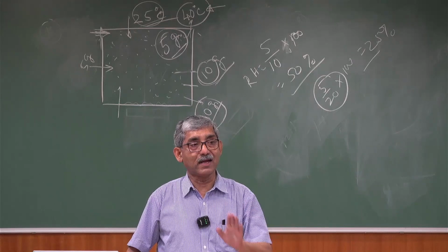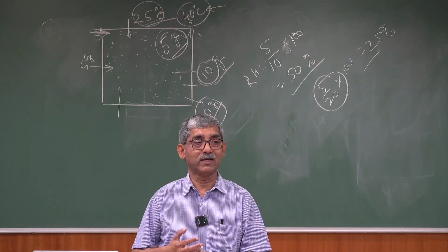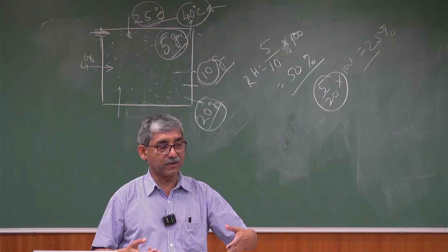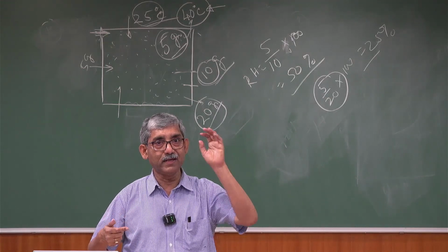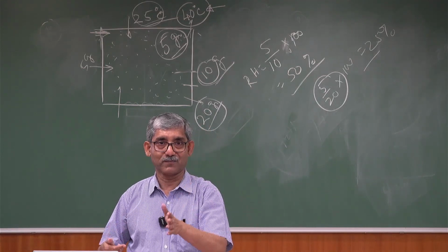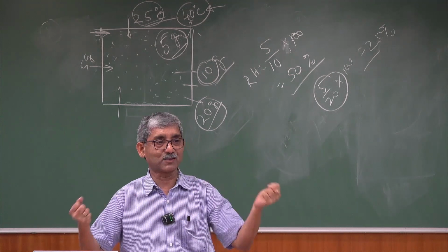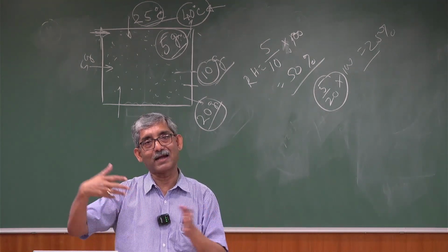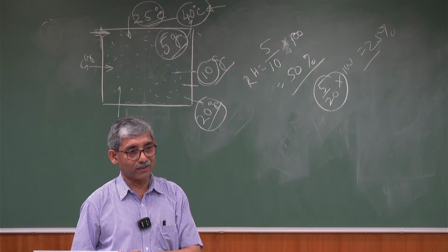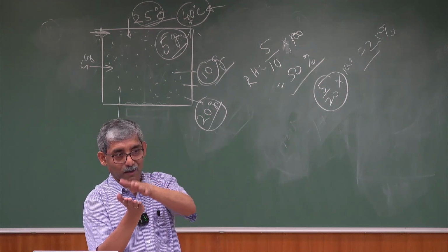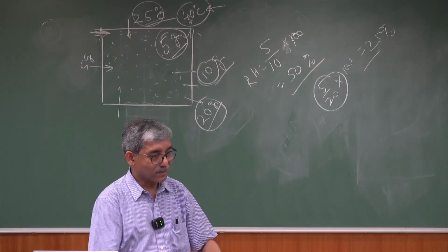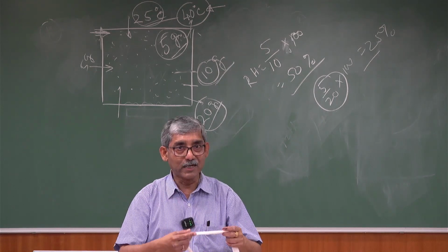Then addition and reduction of irregularity. One thumb rule is that in any production where stretching takes place, that means you are adding to the irregularity, and where doubling takes place, that means you are reducing the irregularity.